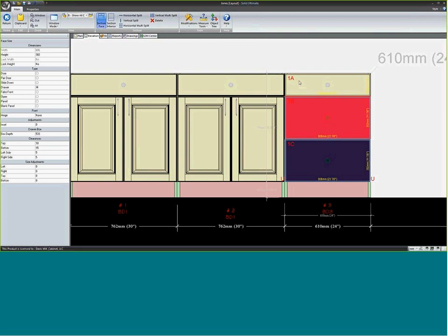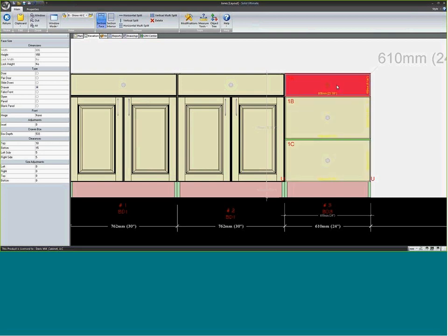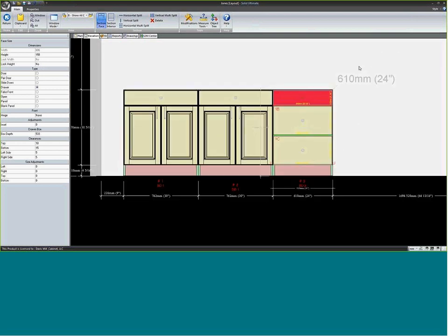It maintains the reveals between drawers. You don't have to do any of those calculations. It does it for you. Over here, you'll see a couple of other things you can do. You can lock the height or width of a section. Sometimes if you get a tall cabinet with 3 or 4 sections in it, doors, drawer fronts, whatever, you'll find that you'll want to lock some of them to keep it from changing the wrong thing. When you alter this one, it changes this one instead of this one, kind of a thing. You'll have to play with those settings. But lock height and width, or right-click and equalize height and width. You can also access lock height and width from this menu too. So that's one thing you can do from sectioning view.